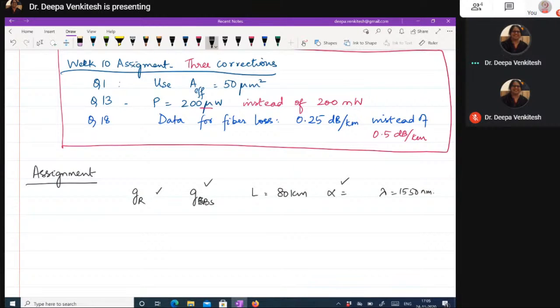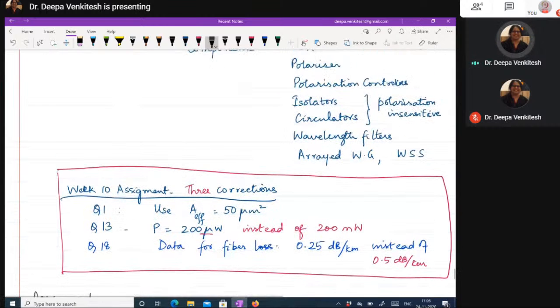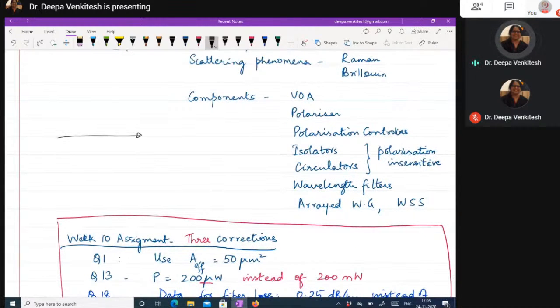To answer that question, if you remember, we discussed this in class that as a function of input power, if you look at the reflected power, this is the Stokes power, which is the reflected power. This is the threshold at which this process starts, this is your SBS threshold, and corresponding to the SBS threshold, your transmitted power, which I'm also plotting, starts saturating.